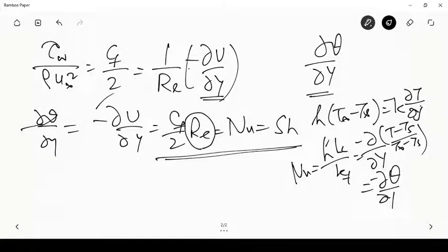Okay. Now today we'll be looking at the solution of this boundary layer equation. We'll try to get what the solution looks like from the order of magnitude analysis on the governing equation. So you will get the form of the solution and not exactly what the solution is. There will be some constants missing. It will say delta is such a function of x, or the Nusselt number would vary with Reynolds number in a particular way. The form of the equation would come, and the exact solution would give you the constants that are missing.